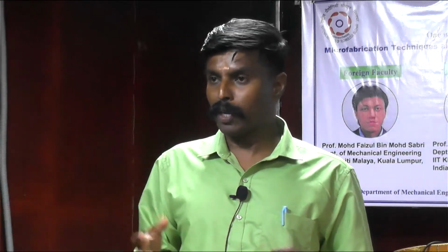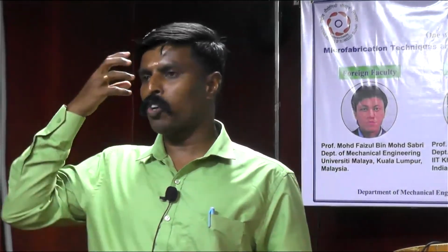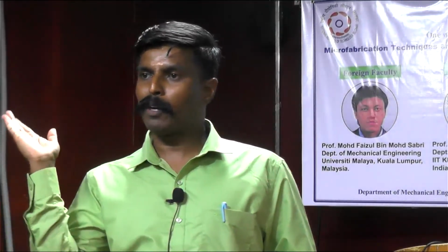High end in the sense of electron beam welding and laser beam welding. The problem with laser beam welding and electron beam welding is that they are costly. Electron beam welding again needs a vacuum chamber, which is all cost. Always go for the cheap and best, that is the performance per cost ratio. As a design engineer, our thinking should always be performance per cost ratio.